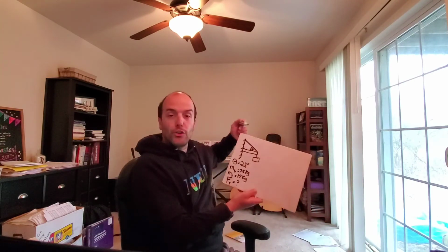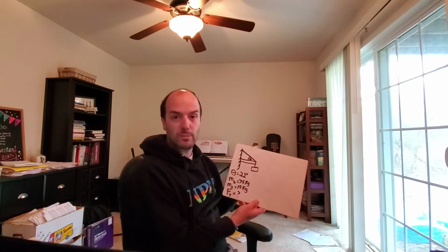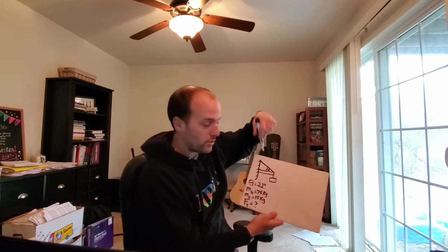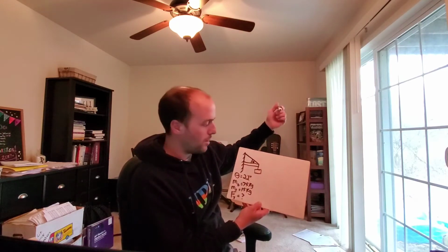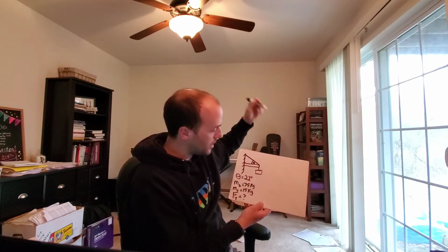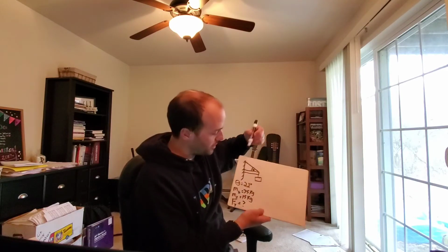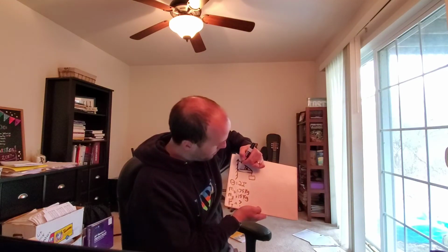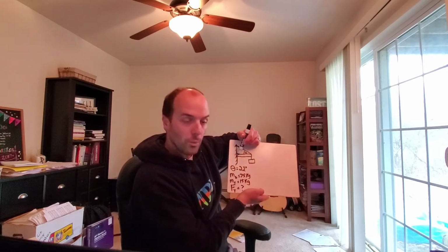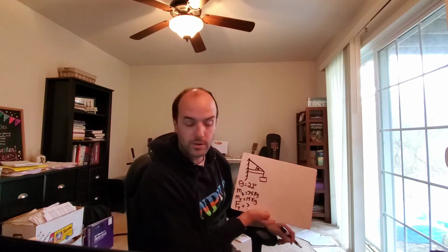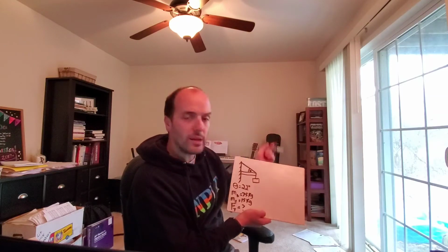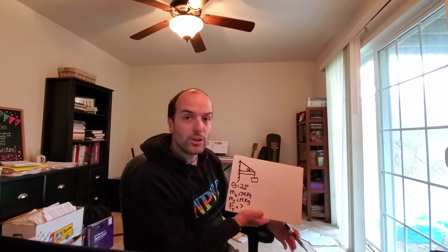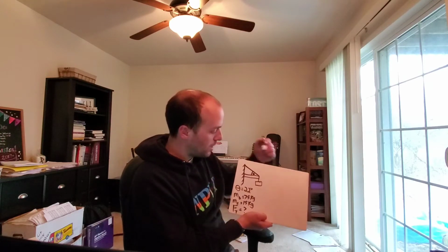Now, earlier in the video, you heard me say that sometimes you've got to pick where you want your pivot point to be. This is one of those scenarios. There's no obvious spot like there would be with a fulcrum or something. I strongly suggest making this point right here, where the beam meets the wall, to be your pivot point. You could pick here or here or here, or in the middle of the beam or wherever, but it will make your job more difficult.